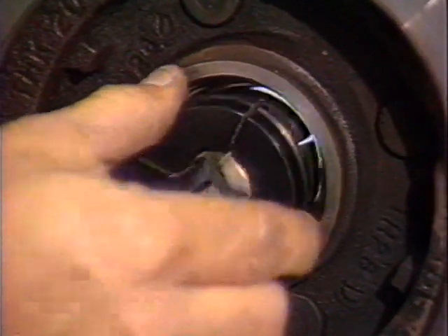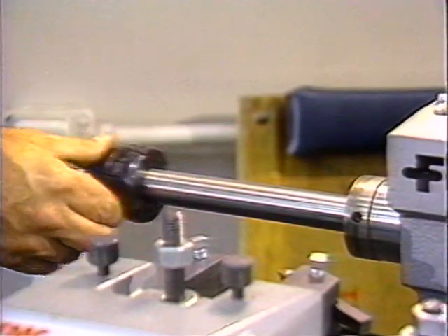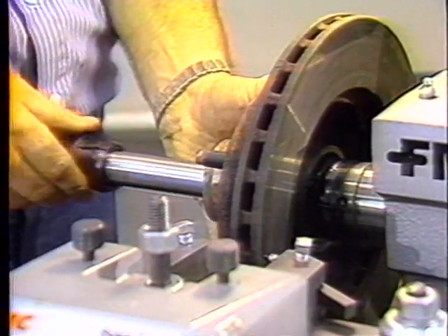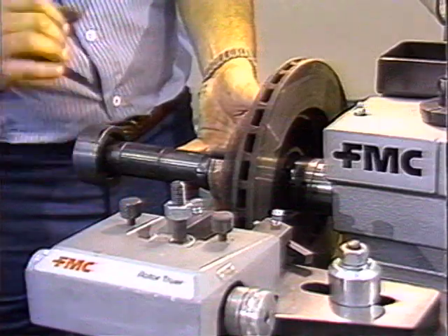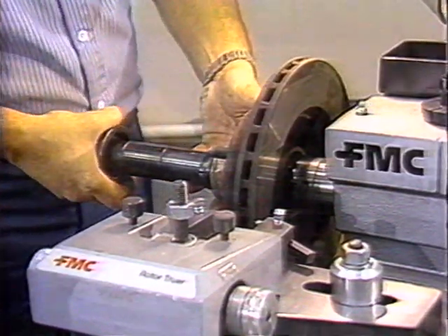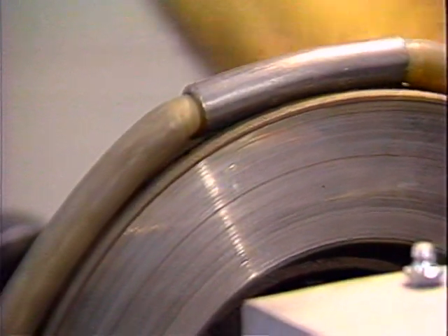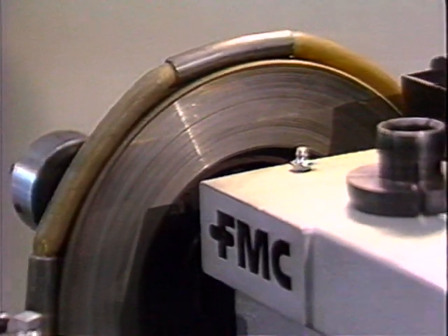Select a collet that fits into and contacts the inner race properly. Select a collet for the front race. Add enough spacers to fill the shaft. Then screw on the left-hand threaded arbor nut. Use the spanner wrench provided with the lathe to tighten the arbor nut. Just snug down the nut, don't over-tighten it.